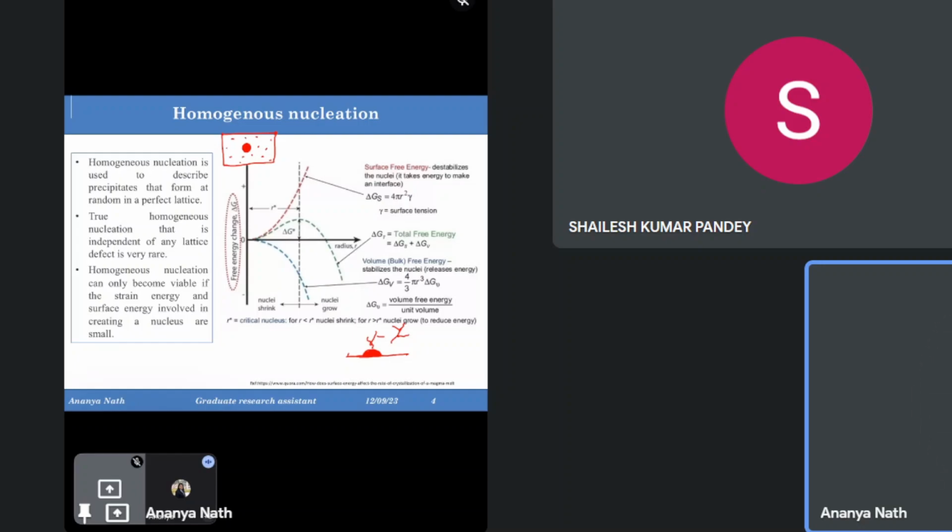It needs to bear that high surface free energy, because as the nuclei grow, the surface energy will be more and more. At the same time, the volume free energy will also increase, and since it is negative in sign, it depends on which direction it is acting. In the war between these two, the nuclei will grow, and with time the graph will go towards the volume free energy zone. As a result, the nuclei will grow and will be called a nucleus.